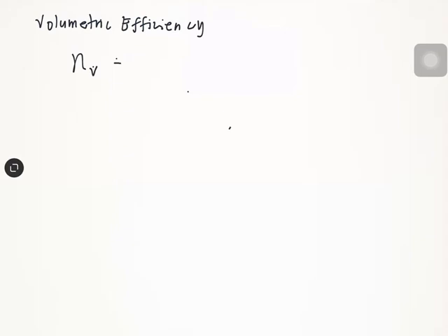Volumetric efficiency. This is defined as the mass of vapor actually pumped by the compressor divided by the mass of vapor which the compressor could pump if it handled the volume of vapor equal to its piston displacement, and if no thermodynamic state changes occurred during the intake stroke.